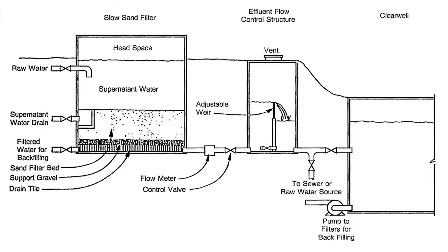So this setup right here shows a second type of filter, which is a slow sand filter. The previous slides were depicting rapid sand filters, which are most commonly used in water treatment systems for surface water. However, slow sand filters are also used in some settings, and the difference here really is that we have a larger head above the filter starting point, so we've got more water up on top of the filter, and the media would typically be finer grain.